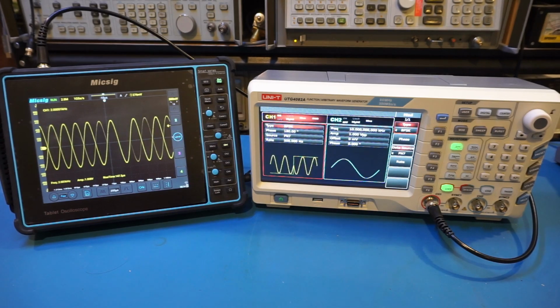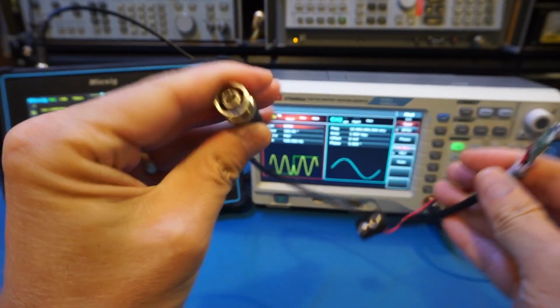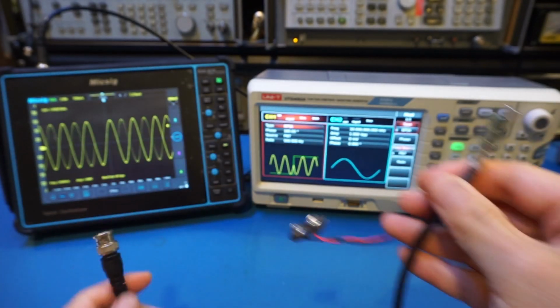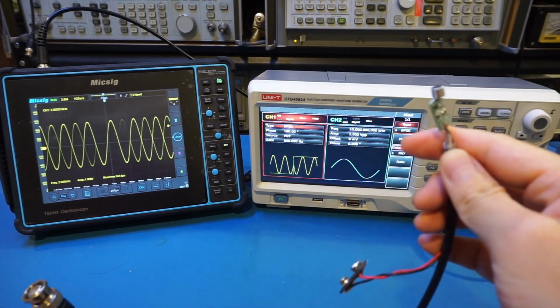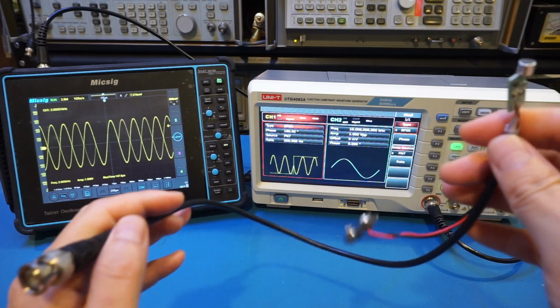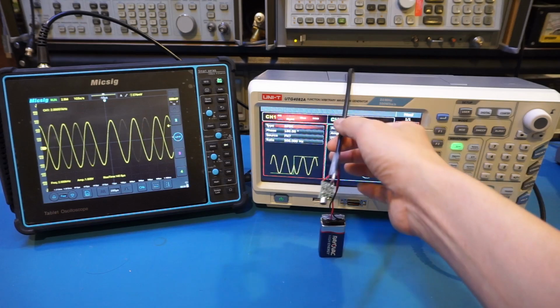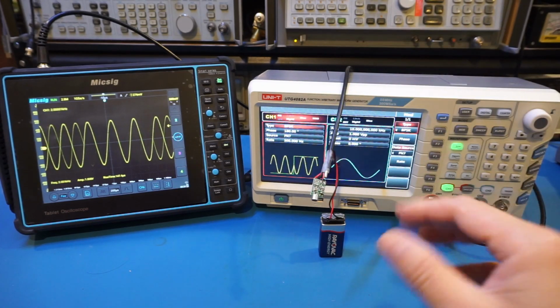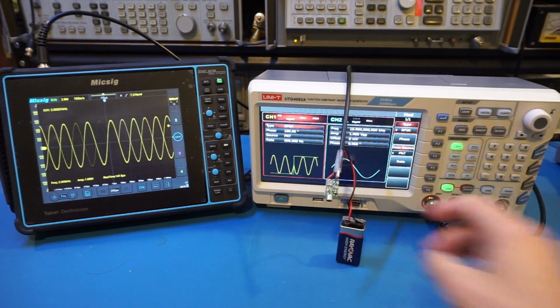Because the UTG4082A supports external modulation, I can actually use it to demonstrate how an AM radio transmitter works. So here I have a simple microphone amplifier circuit board, and the output is connected to a BNC, so I can plug it into the external modulation input. And of course, it's powered by a 9-volt, so there's nothing fancy. So let me actually hook it up, and we'll take a look. All right, I have plugged it in. The BNC cable is a little bit short, but nevertheless, I plugged it into the external modulation input and also powered on the circuit board with a 9-volt battery here.